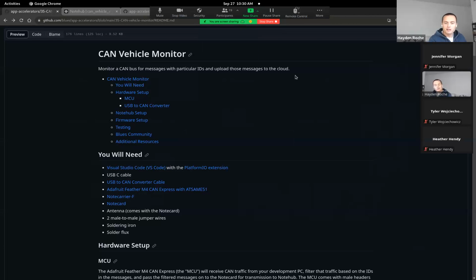So if we have any automotive folks in the audience or aviation folks, also industrial controls folks, you might be familiar with CAN, but it's essentially a bus that was developed for cars, trucks, what have you, to allow all their ECUs or electronic control units to communicate with one another and save wiring, essentially. So CAN is in every modern car, and all the little computers, dozens to hundreds, depending on the model of car, are using CAN bus to communicate with one another.